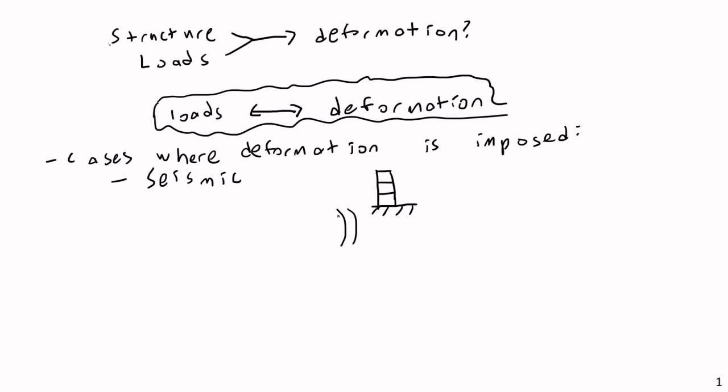So, in other words, what I'm really getting at here is that in seismic loading, the ground does what it wants to do. If it wants to move over an inch, it's going to move over an inch. Your building or your structure is not going to noticeably affect the motion of the ground underneath it, because again, this chunk of the Earth's crust is wanting to move to the right, for example, at 1 inch or something like that. This chunk of the crust is going to move, and it's just going to carry the foundations of your building right along with it.